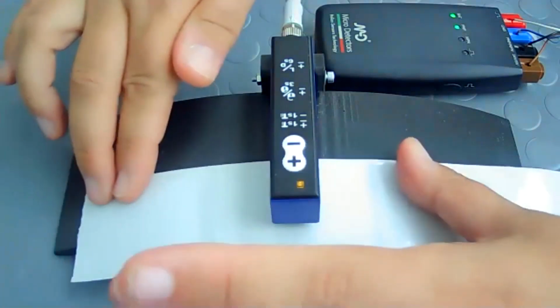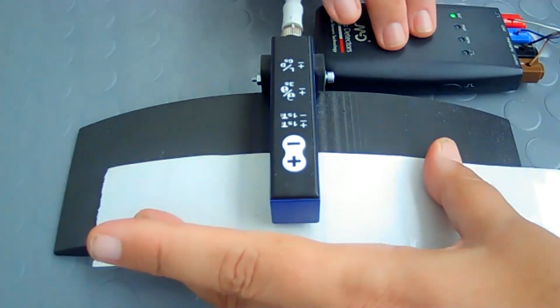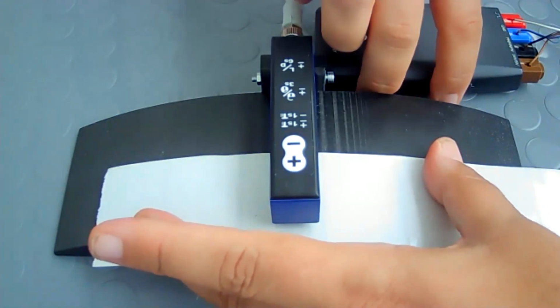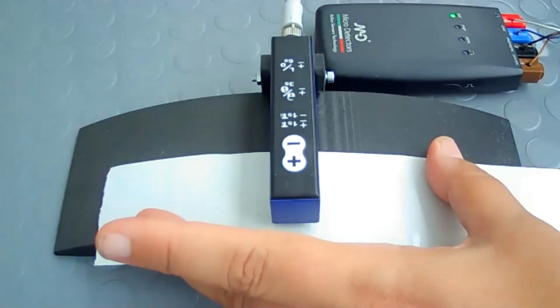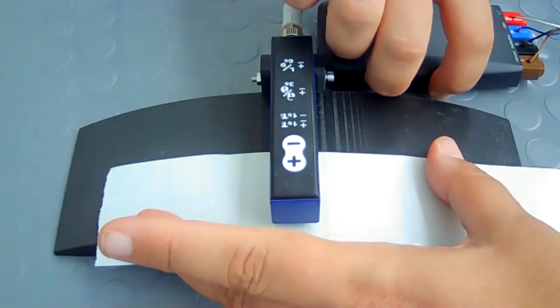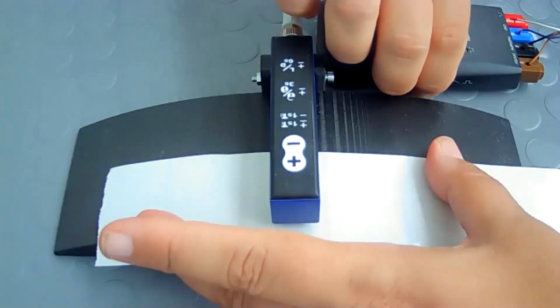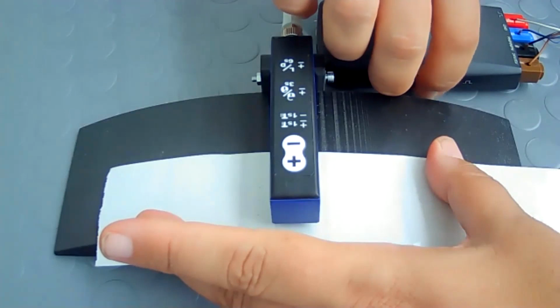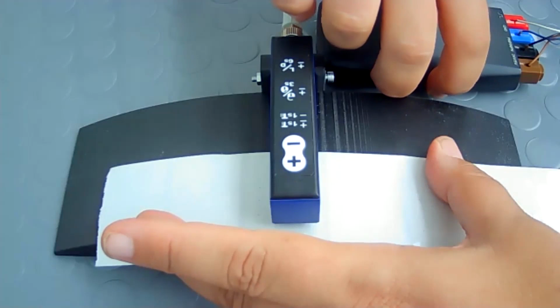Of course, the identification of the edge of a single label is shown through the yellow LED. Now we can show you how to adjust this sensor in remote mode, so via cable. In particular, you have to use the white wire and connect it to the positive pole, as Fabrizio is doing now.